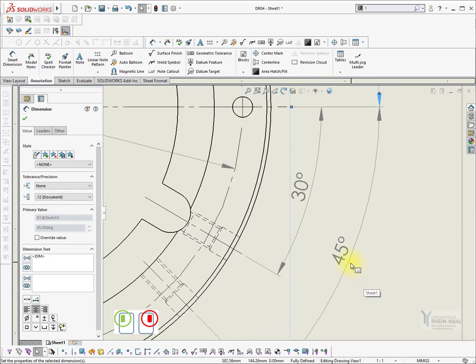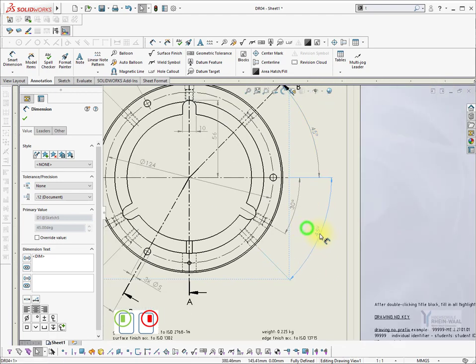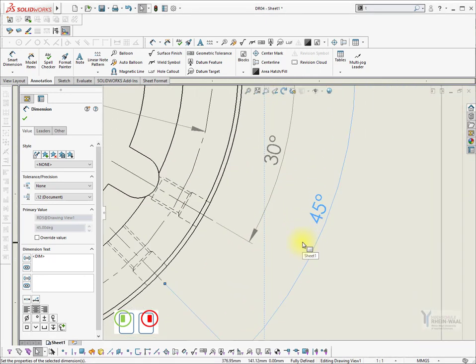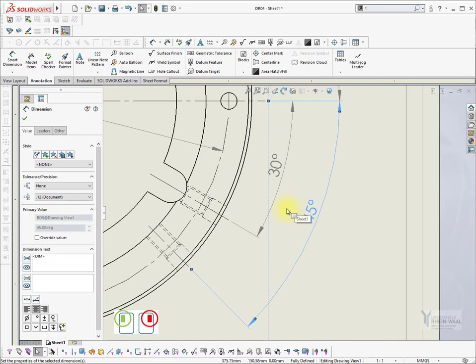You can sense for preferred positions. See the yellow lines. SolidWorks tries to refer positions to other entities, but this is not always helpful. If you want to avoid that, simply zoom in and it cannot see the other entities. Same thing.